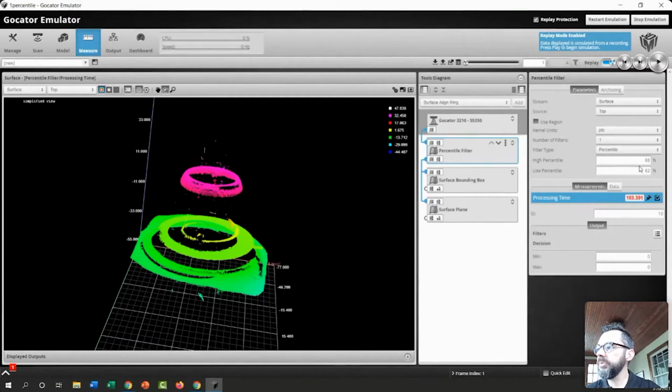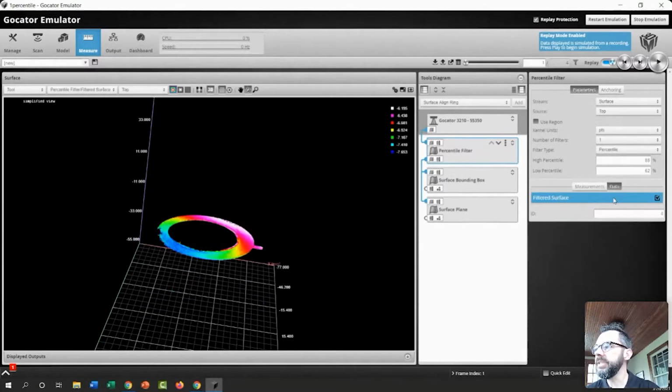And just like with relative threshold, we have a high percentile and a low percentile. What that allows me to do is not only isolate a specific percentage of the data within that stack or column, but drive that to a particular location within that stack as well.